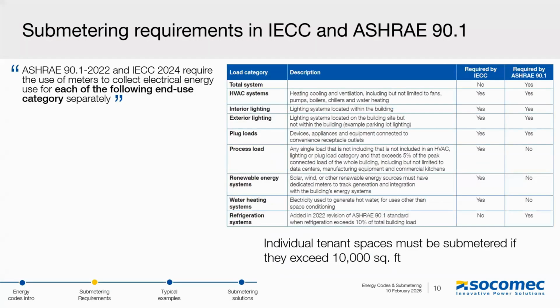So let's look at the submetering requirements in IECC and ASHRAE 90.1. So very, very similar. Like I said, they're kind of tied together. There are nuanced differences, but the requirements are closely aligned. The big requirement is that both ASHRAE and IECC require the use of meters to collect energy use for each of the following end use categories. So a separate meter for each of the different load categories. And the load categories are shown on this table.